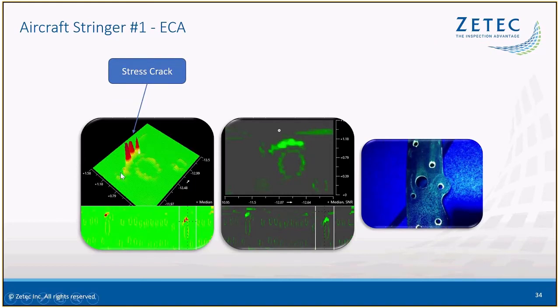the indication occurring. You can also see that there's more going on with the crack than just a single continuous crack. There's variations in the size and depth, and you get that information when you use eddy current array. You can go in and do analysis on what's really going on in there, and sometimes that's important for how you're going to respond to that indication in that part.